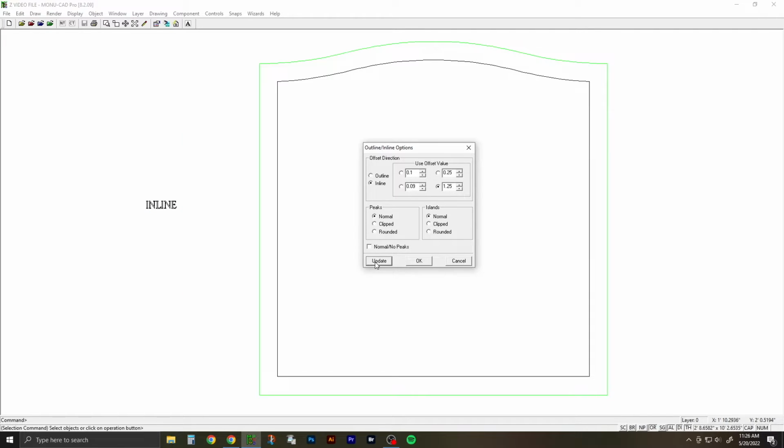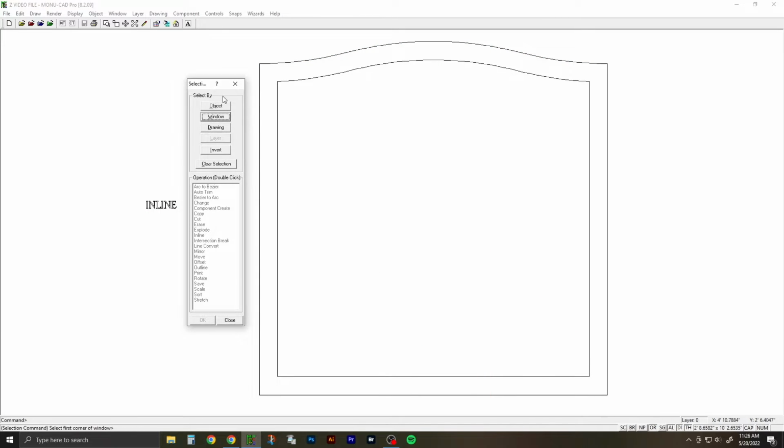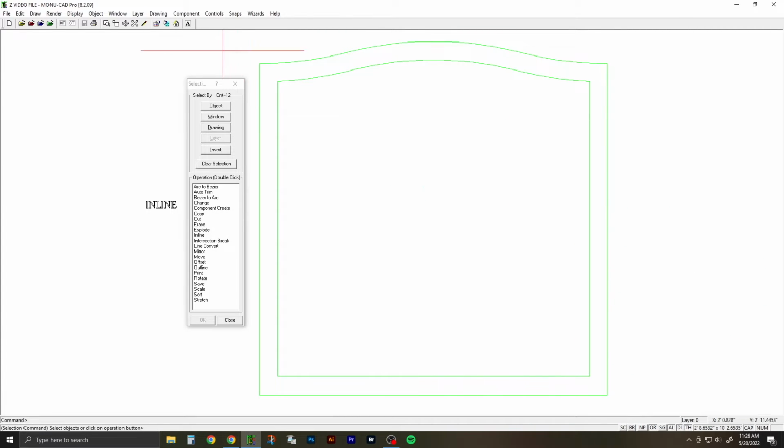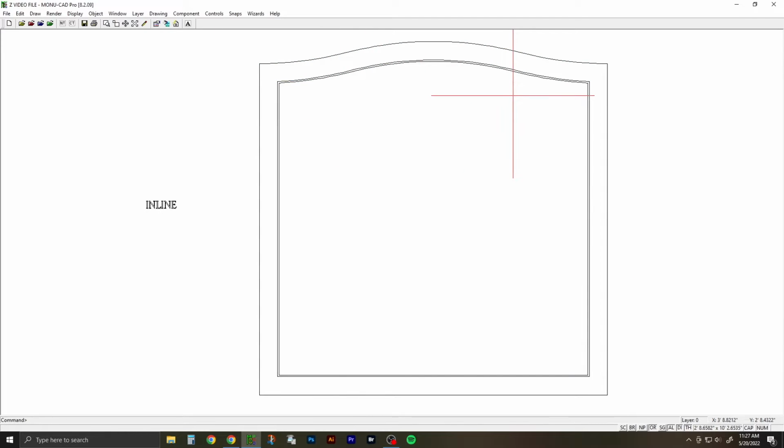And it gives us a 1.25 inch panel. So now we're going to go back in and add our V-line. We're eventually going to make this a double V-line panel, but I'm going to choose 0.1. That's our normal V-line size. You put in whatever your V-line size is. So now we have a V-line.